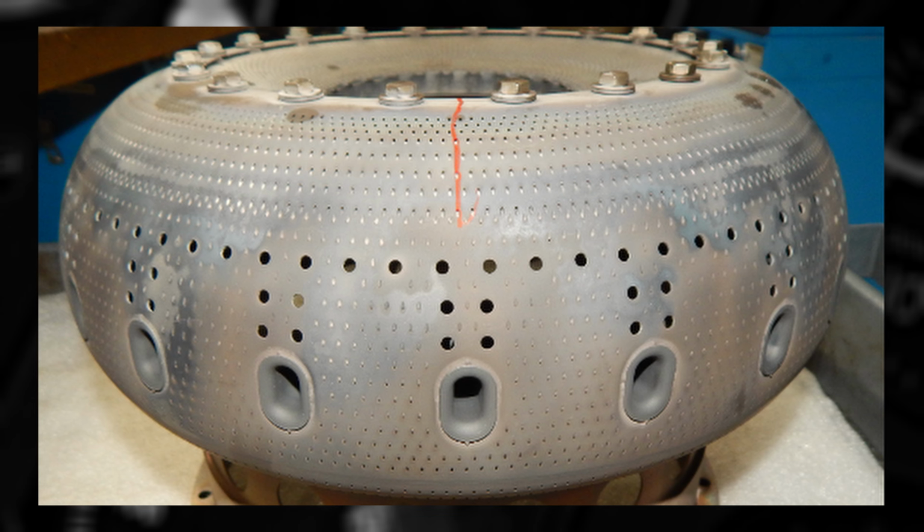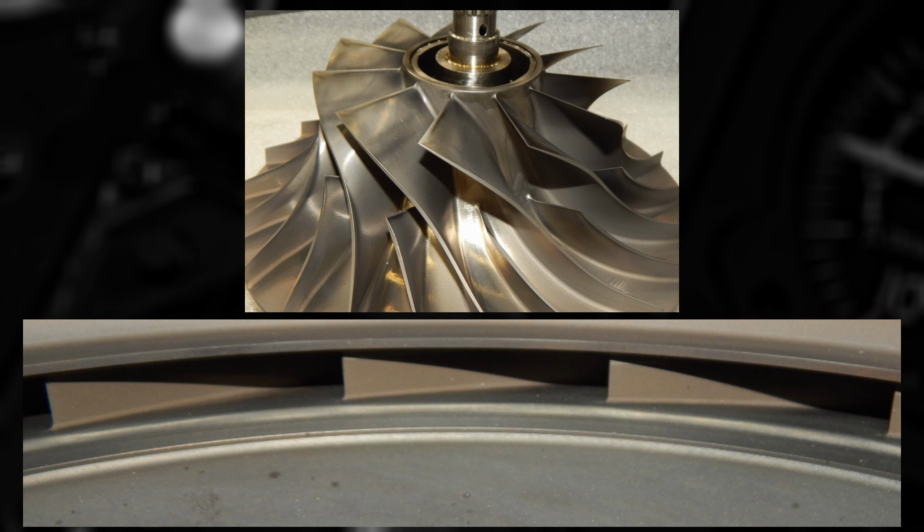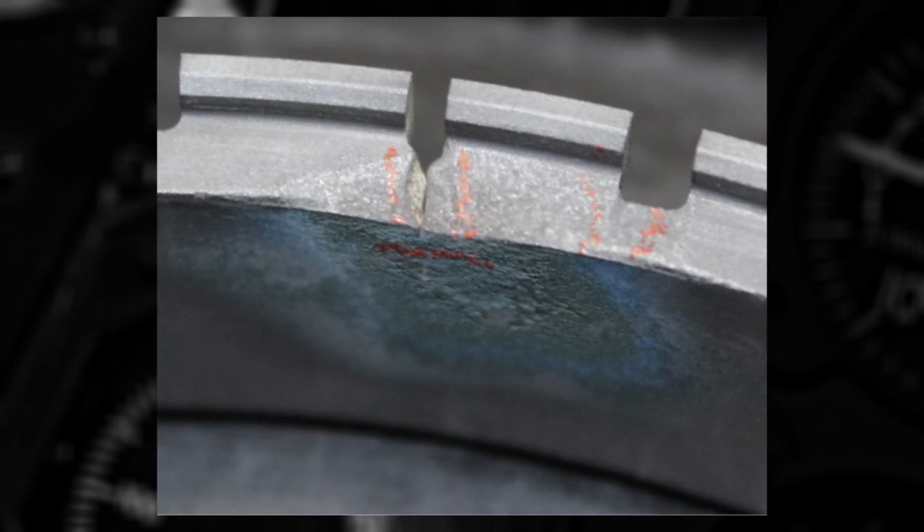Compression stages prior to the combustion chamber are generally cleaner with no erosion, but byproducts of the combustion process are corrosive and accumulations must be chemically cleaned to prevent damage to the high-pressure turbine blades. The high-pressure turbine blades pictured here are from a barrier-filtered Arriel 2. Untreated combustion byproducts have corroded and eroded the tips of the blades.